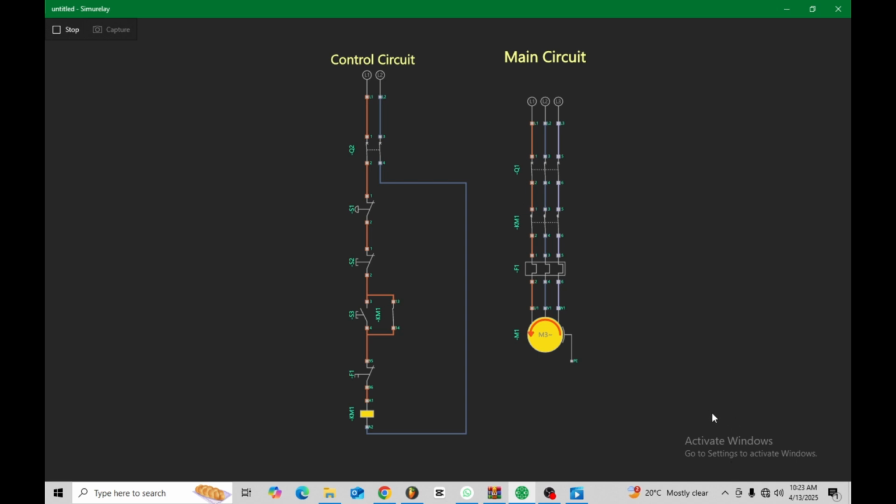direct online starter. Like I said, this is something that you should write down, memorize, and know, because every single motor-based or induction motor-based circuit is based on this circuit over here, direct online. If you want to do forward and reverse, it starts with direct online. If you want to do sequence one, it's direct online. If you want to power slip ring motors, it's also direct online. Even single phase forward and reverse is also direct online, or kinda. It's kinda like direct online.